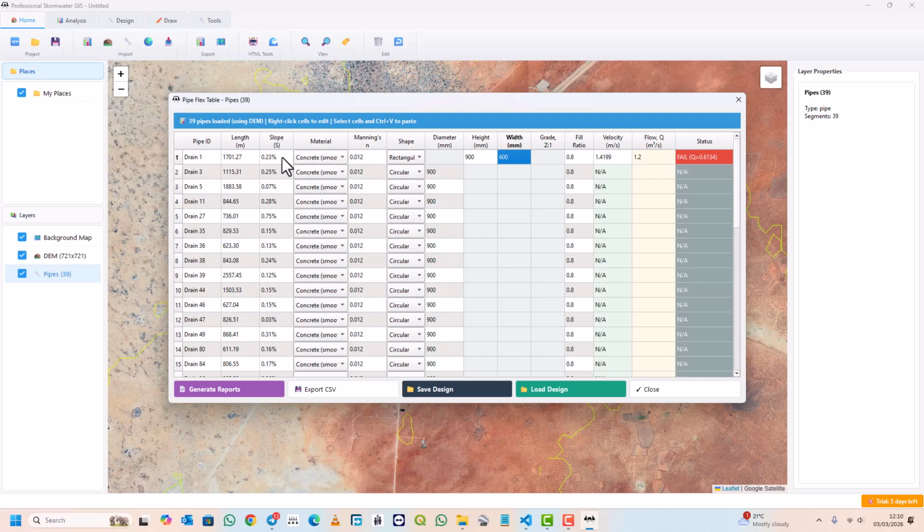Okay, 600. Then we can increase this one to 0.75 and see, it's almost. So we can just go with 0.8 or 0.85. Yes. So if this one is not working, considering your Q, this amount of water is also too much. So what you can do, maybe you can increase this one to 1200 or 1000, and this one 600 or 750, something like that. So with this, that is okay, and then you can just click save.